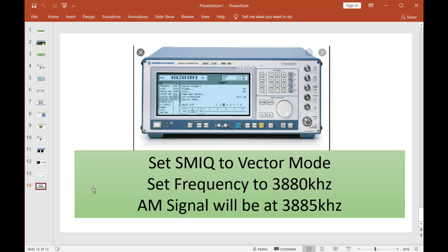And stay tuned for more videos on this Red Pitaya thing. Based on what I've studied, if it works as good as it seems to, it might very well be the best HF exciter for 300 bucks, bar none. And I'll get into it later, but the real reason is because the IQ modulation in the Red Pitaya is being done entirely in firmware. So all that is being done behind the DAC, and what that means is that all the IQ imbalance and everything is minimized because it's all done before the DAC and it's being done in firmware.